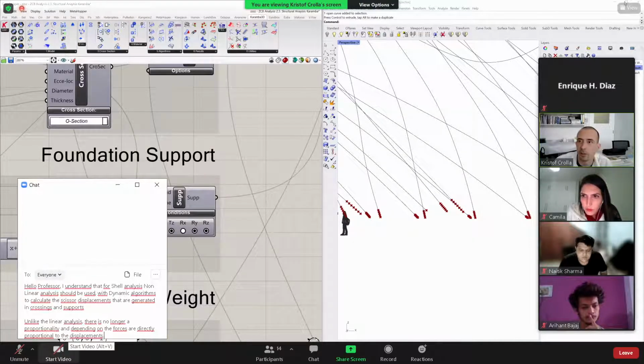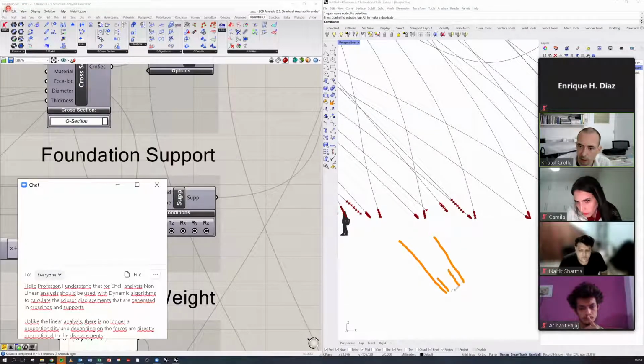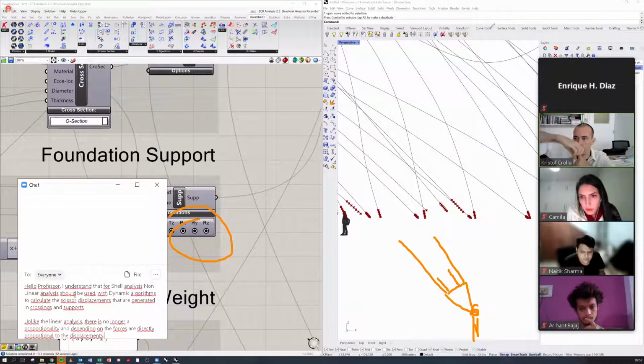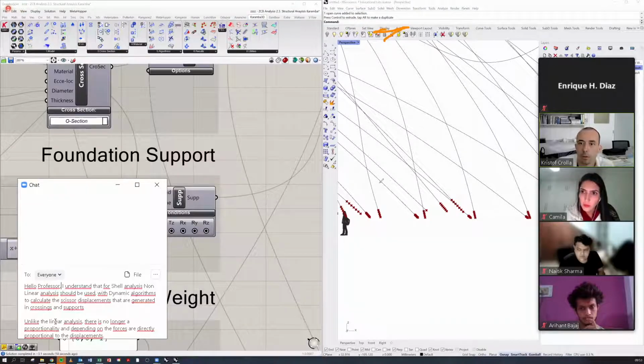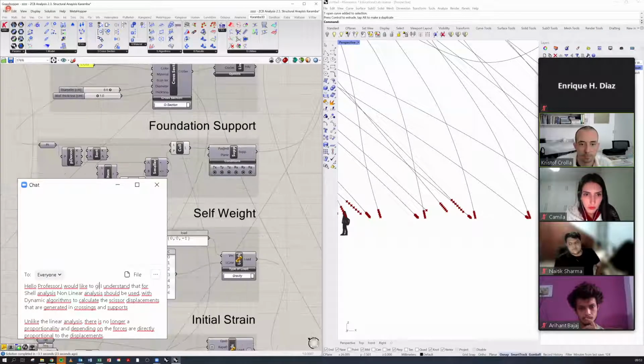Some of the details that other bamboo structures have had is where people at the end make a steel gasket or something that sits inside the bamboo pole, and then with a ball joint it is connected to the ground. If you would have that, then you would basically switch off all your rotations. You basically have a bamboo pole that can rotate around. So that's straightforward. Clear all drawings, close. So that's the supports that go in.